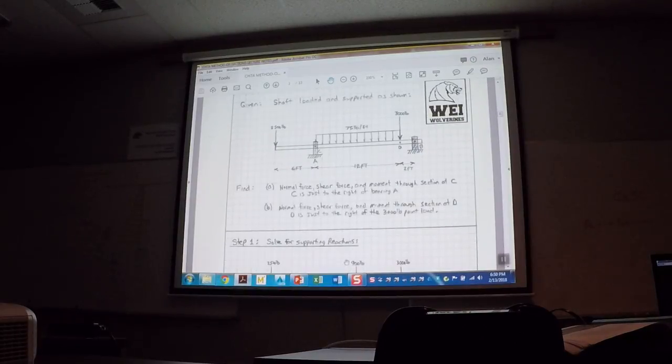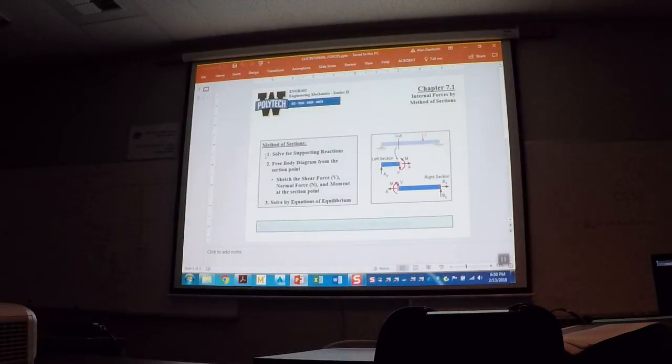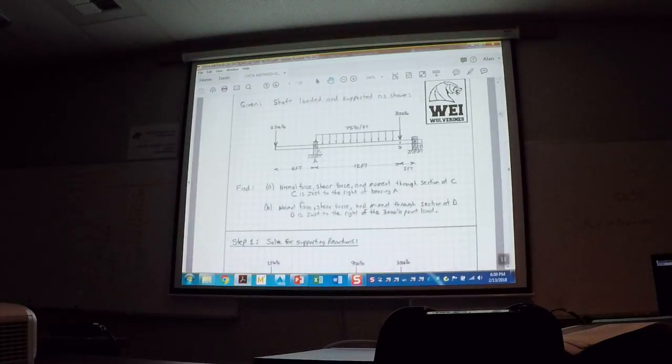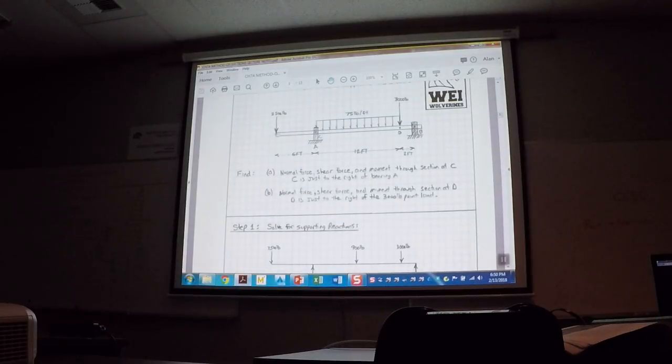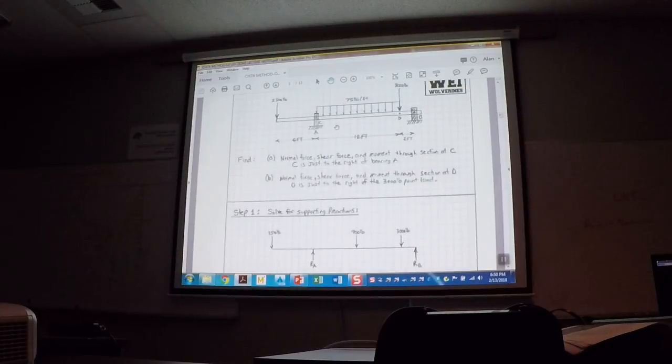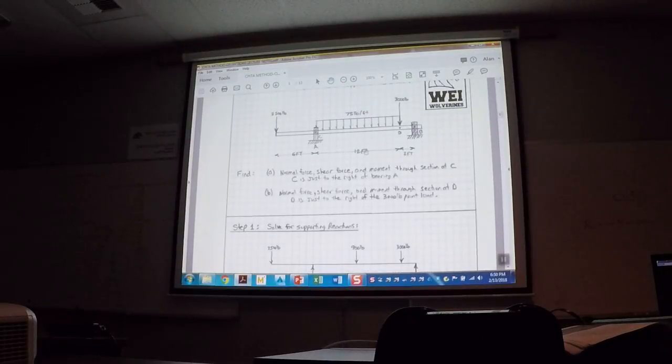All right, so step one, right from our handout right here, step one is solve for the supporting reactions. So the supporting reactions are reaction at C, basically a vertical, and reaction at B, vertical. So what I did is I did a little free body diagram and acted like this was just a beam, and that these supports, I removed the sketch of them and I just put point loads on. Also, this distributed load, I just took, what's that, 12 feet? 12 feet times 75 pounds per foot, and I did a load right at the center.